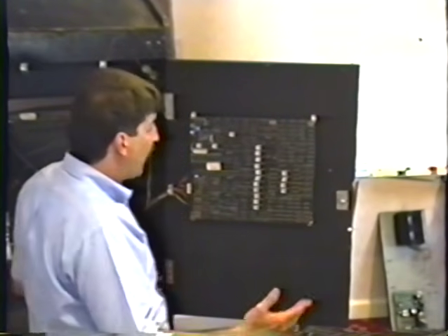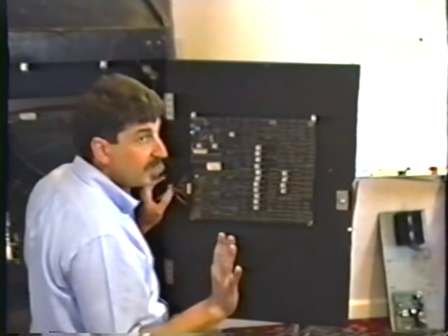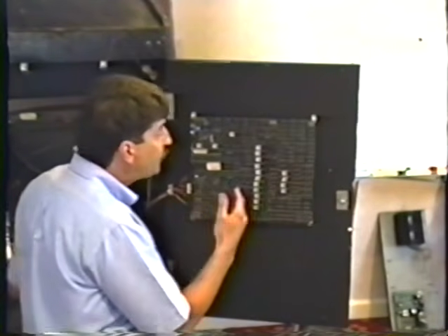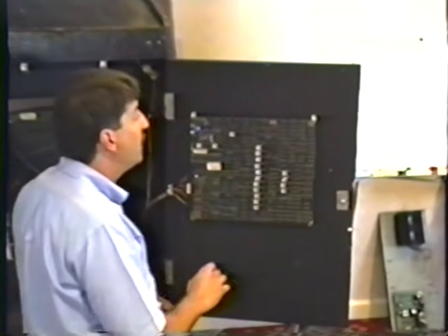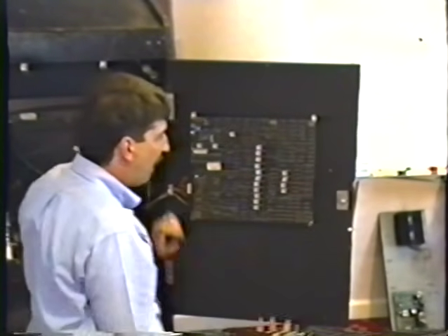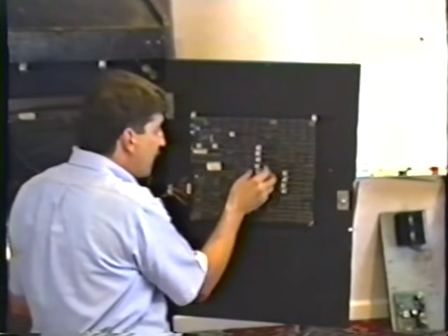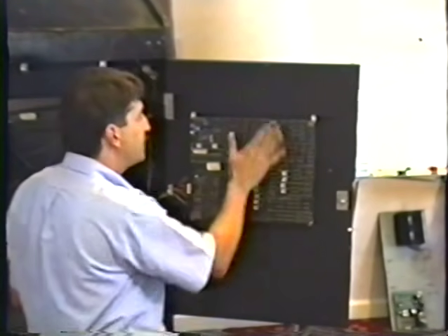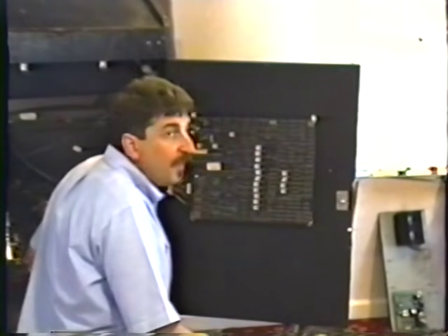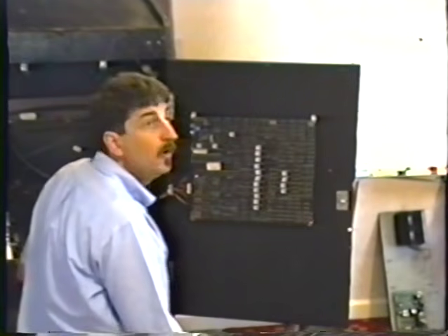So again, you get to the game, it's got this weird junk on the screen. First you check the power supply, because that's the most likely cause of that problem. But if all the power is okay, you definitely have a board failure. Don't give up. First, turn the power off, push on all the chips, and turn the power back on. Does it work? No. Carefully pull each chip out one at a time that's in a socket, clean off the pins as necessary, put them back in, fire it back up, and see what you have. That really solves a lot of problems. I never send a board away without doing that first.